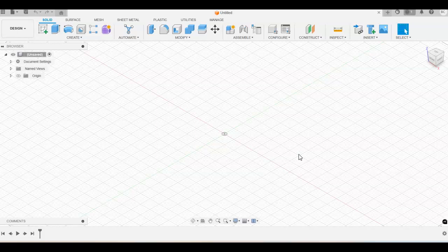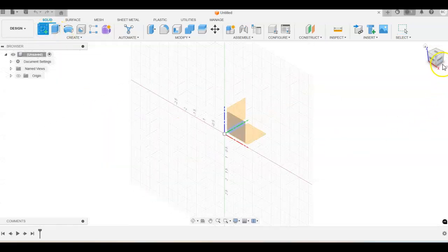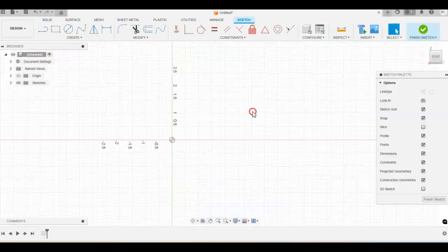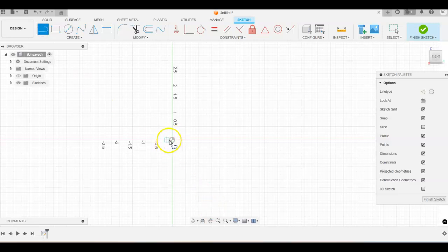Now on the top view, we see those object lines where that oblique angle gets cut out, and then the rest of our dimensions are coming from the side view. So I'm going to start this particular sketch on the right side view, so in our profile, and I'm just going to use my line tool, and then I'm going to go back and add some dimension constraints to it as well.